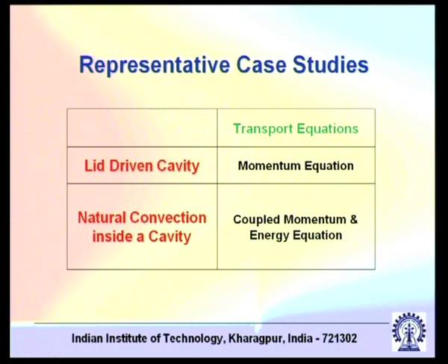Now we will go through some representative case studies. Two of the interesting case studies are, one, lid driven cavity flow. There is a cavity in which the top lid is driven with a particular velocity and that induces a motion. This is a standard benchmark problem in CFD, known as the lid driven cavity problem. And then natural convection in a cavity, where you need to solve coupled momentum and energy equations.